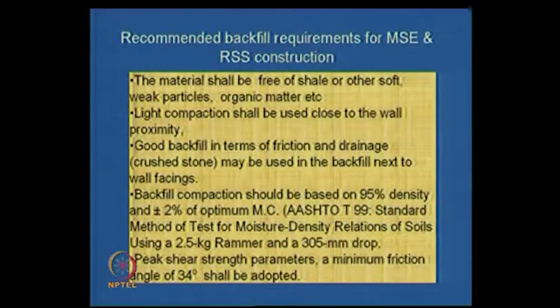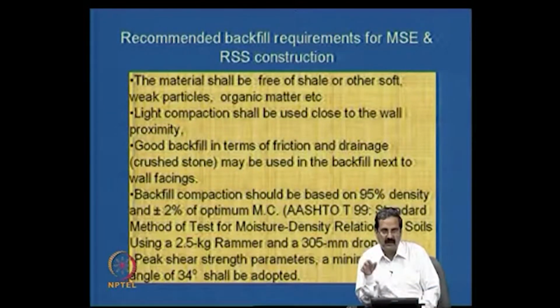Then, light compaction. Backfill compaction is alright, but close to the wall you have to use a simple light compaction method, light compactors. One should use them, because if you use heavy compaction equipment, a lot of stresses come onto the wall, and even compaction control is difficult. They exert additional stresses. So, the best is to have light compaction equipment, and also good backfill in terms of friction and drainage,